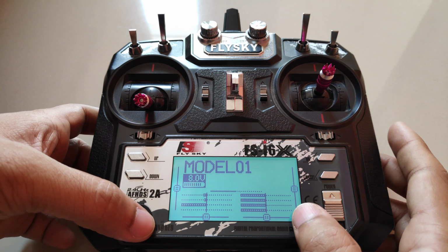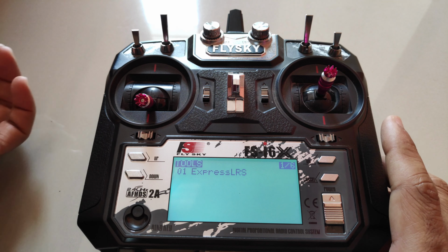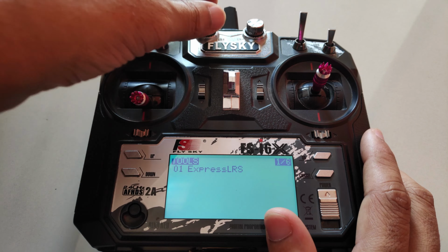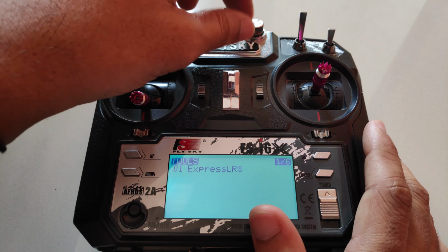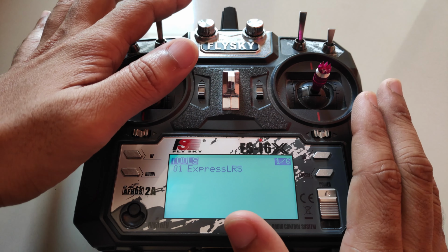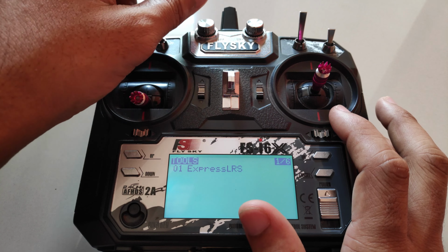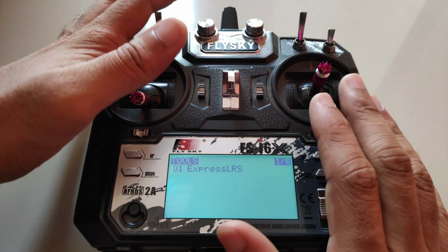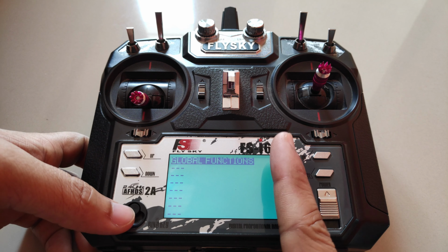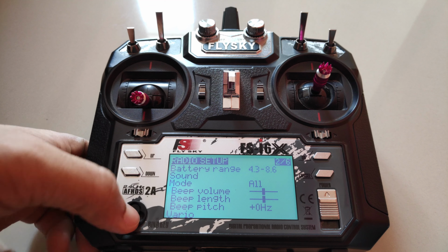Now the next improvements are in the radio setup. If I hold the bind button, the first is the tools page. With the previous version, we could navigate between the menus with the pot, but that's been disabled because sometimes that was annoying, and sometimes the settings would accidentally change by scrolling the pot. So that's been disabled. And on the better side, we can navigate to the previous page by holding the bind button.